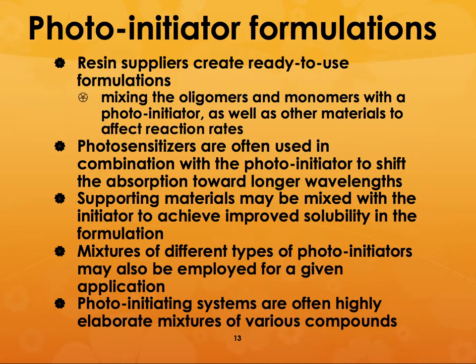You might have to add what are called photosensitizers that can combine with the photoinitiator to shift the absorption towards longer wavelengths. The reason why we want longer wavelengths is because they have lesser energy, which means that people who might get exposed to it by any chance might not get affected by it. I mean, suppose you put your hand below that laser beam, longer wavelengths are not going to affect you. But shorter wavelengths can penetrate a larger distance into your skin or your body.